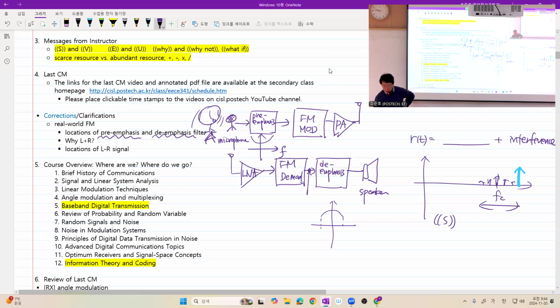the FM modulated signal with message, what? No message, actually. So m(t) equals 0 means, as you remember, we still transmit a tone, right? Single tone. So here we have a single tone. And if this is received, then what happens? The FM demodulator output will be 0 if we have a DC block circuit. However, due to this interference, which is also, for simplification, modeled as a tone signal with some frequency offset from the carrier frequency, that appears as a very loud tone signal.